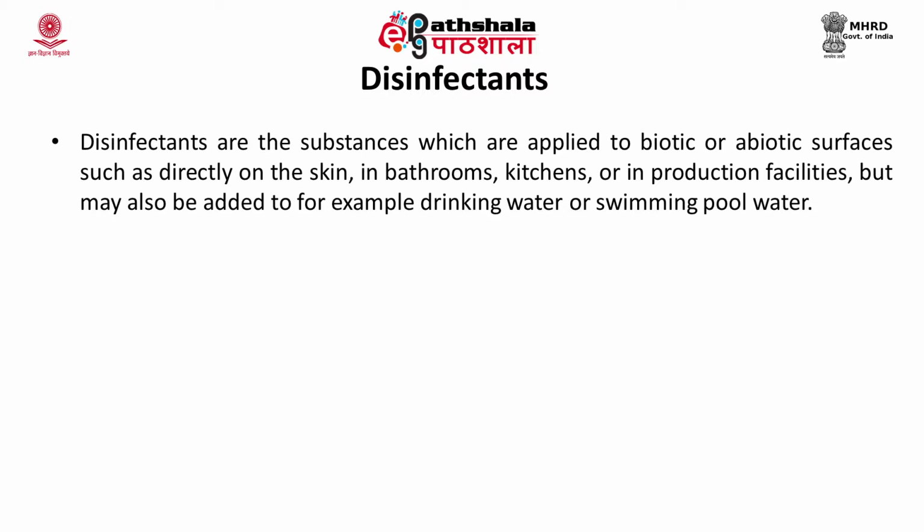The disinfecting agents are registered by the Environmental Protection Agency as antimicrobial compounds, and these are substances used to control, prevent or destroy harmful microorganisms like bacteria, viruses or fungi, and they must provide 99.9% inactivation of the microorganisms, their cysts and enteric viruses to protect health.